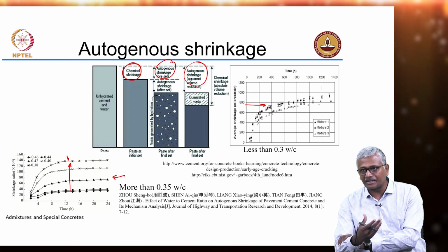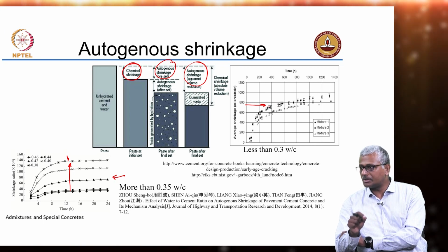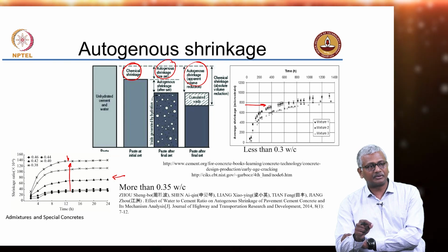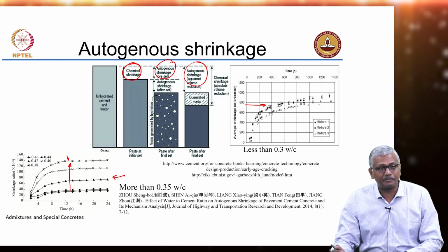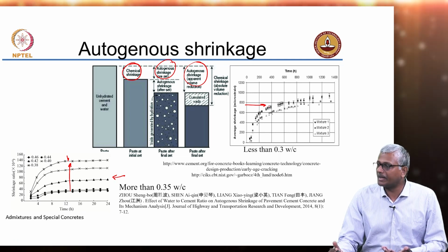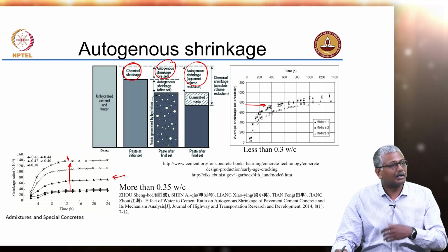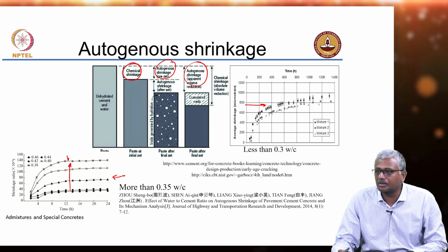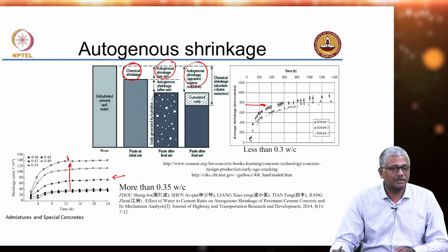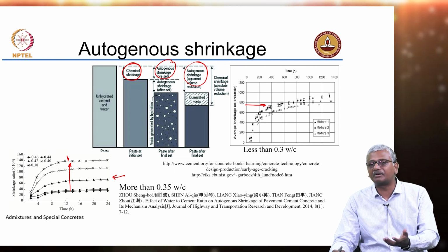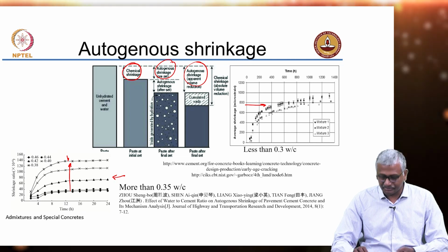So, reinforced concrete design itself has to start accommodating these numbers, and for this you need to actually do a calculation to determine what is the possible shrinkage that can develop in these systems. And for that you need to do concrete mixture design over a certain period of time to understand what are the stresses or strains that are happening because of shrinkage and thermal effects, right. Essentially I am trying to convey is that when you are designing special concretes like this, you need a significantly large amount of time to really answer all these questions that will ultimately feed into the reinforced concrete design, to accommodate the strains because of thermal effects and because of shrinkage, right. You can't expect to do a normal concrete design and then get away with it. All these problems will creep up during the early stages of your concrete. You need to counter these effects appropriately.